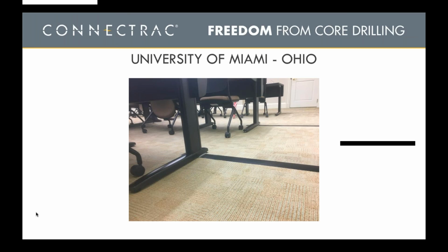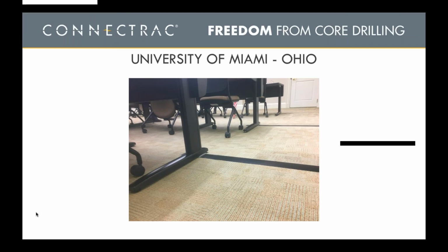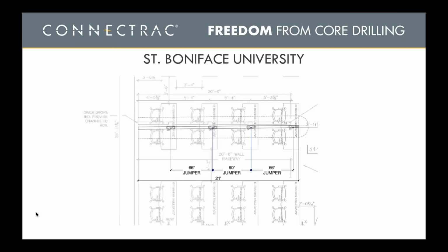So they were not going to use power poles. That was a no. But yet they needed the power, and they needed a dual workstation at every desk in this architectural studies historical building. So they brought wireways from the side walls to under the table, feeding the data cables, and the power were routed up the table legs and attached to the tabletop device purchased with the tables.